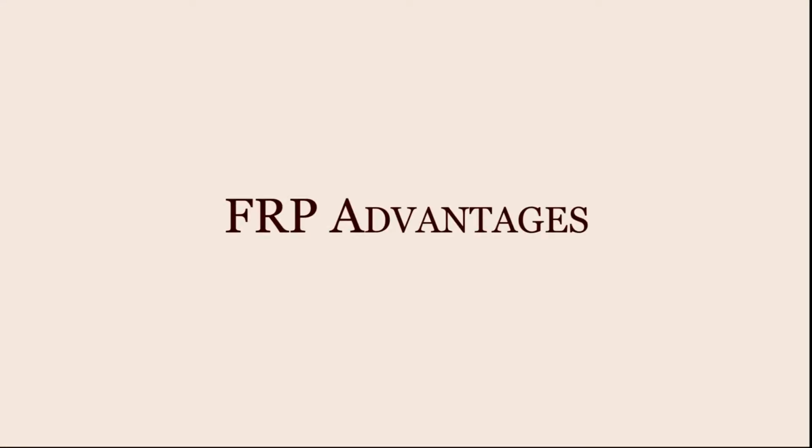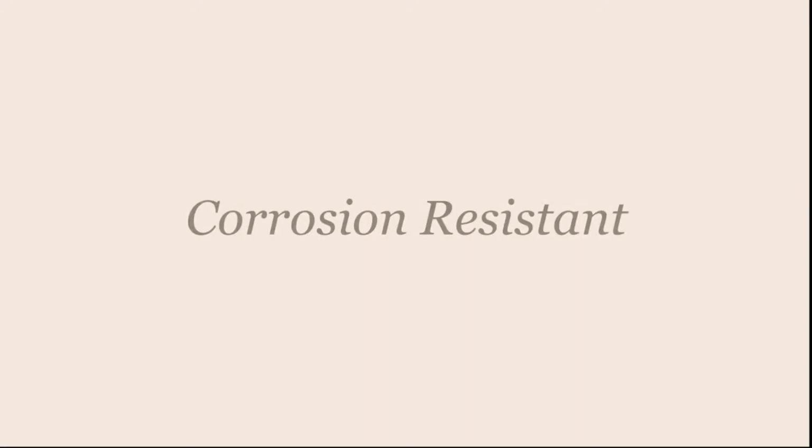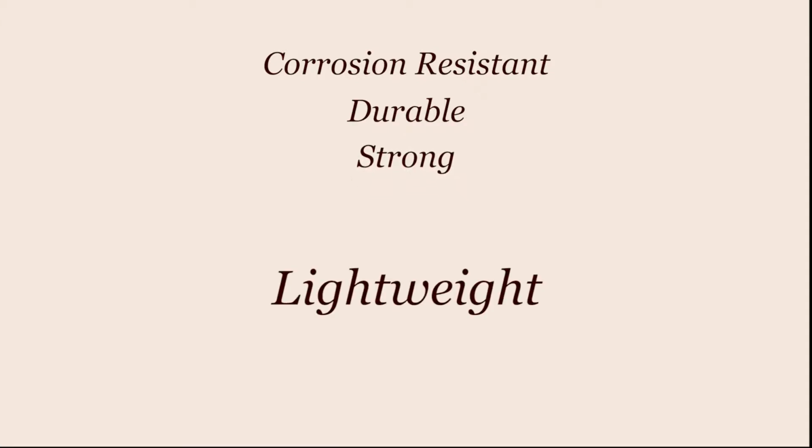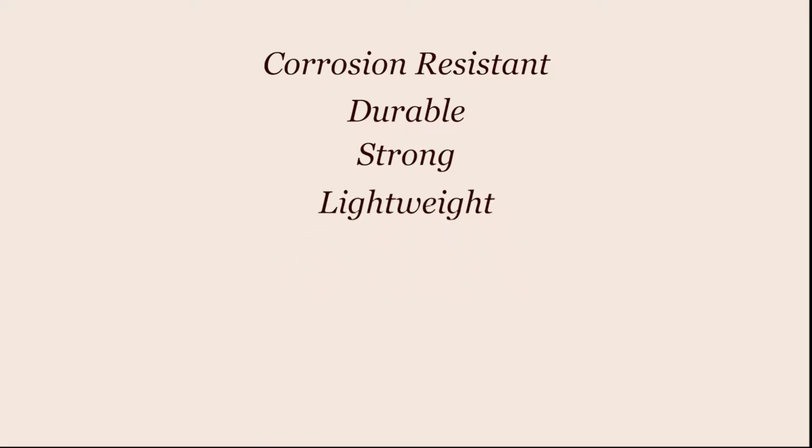The advantages of FRP include the following. FRP is resistant to a wide range of chemicals and is salt and freshwater proof. FRP will not rust and is resistant to termites. FRP does not warp or rot and is resistant to attack by insects. FRP has a very high strength-to-weight ratio compared to metals, wood, and concrete. Pultruded, or PFRP shapes, generally weigh 75 to 80% less than similar steel shapes and 30% less than similar aluminum shapes, making them easier to transport.